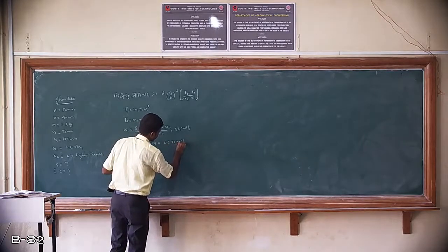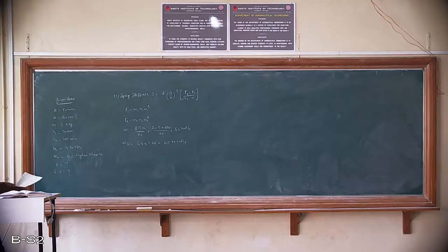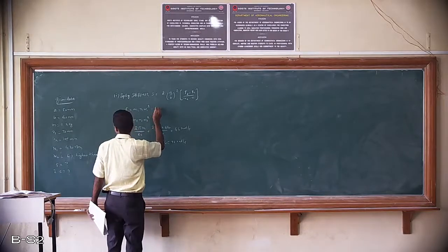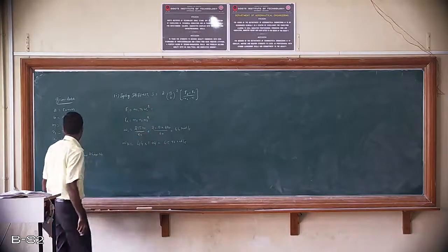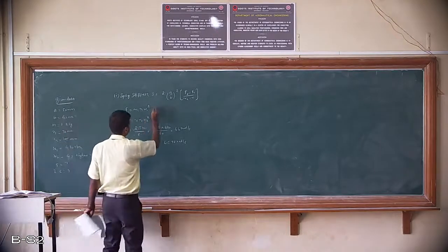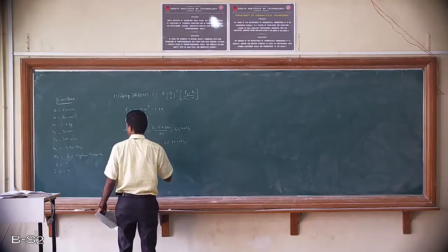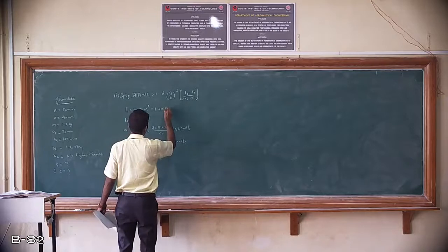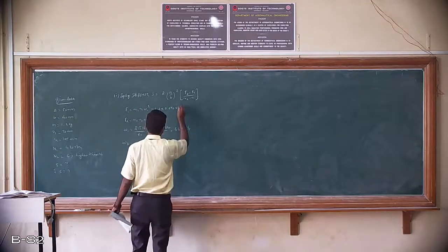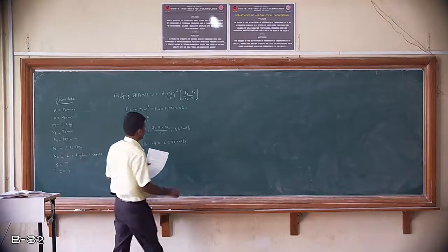The value for omega 2 is 45.76 radian per second. Next is to calculate the value of F1 and F2. So F1 equals M1 R1 omega 1 square is the equation. The mass of the ball is given, that is 1.2, multiplied with R1, that is 70 mm, so 0.070 into omega 1 is 44. So you get the value for F1 as 162.6